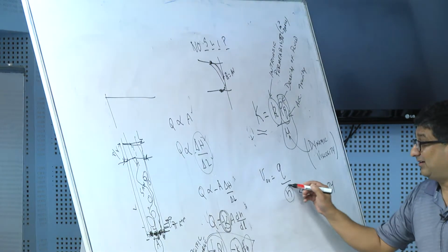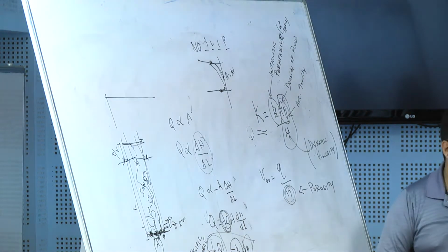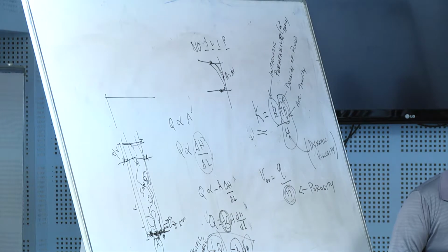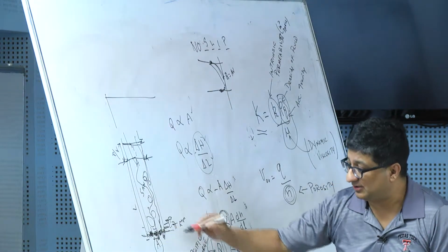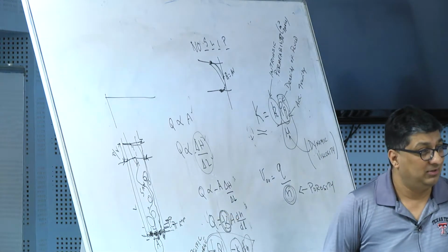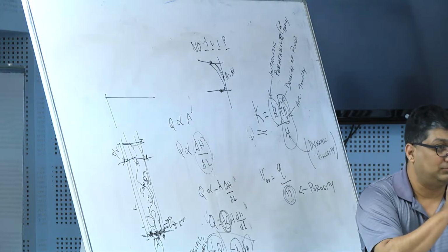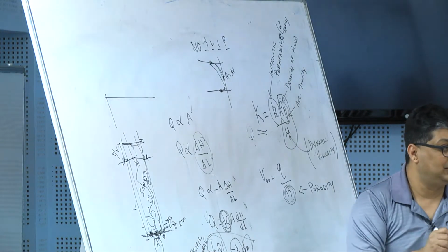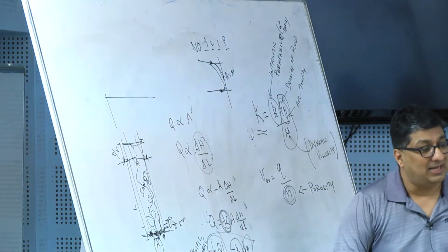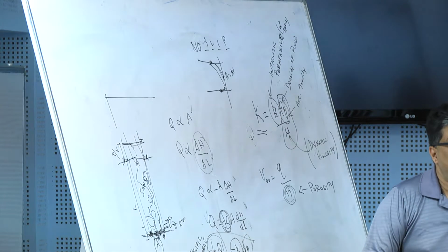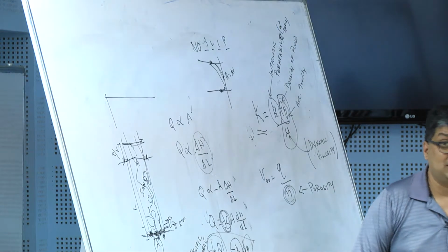The same thing here, by dividing by porosity, I'm dividing over all the range of pore sizes. So this is called the average linear velocity, on average. But if I look at any cross section, if this pore is very small, the water will be moving much faster. If I have a pore that's larger, the water will be moving a little slower. So there is a range of velocities happening across this, but I can only talk about velocity when I'm looking at the pores, not when I'm looking over the entire cross section. What Darcy velocity does is it looks over the entire cross section.